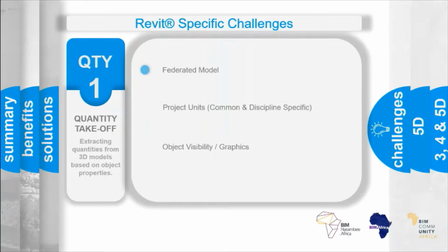It's also important that we manage the coordination of elemental ownership between the different design disciplines, and we'll need to address that in a BIM execution plan in order to prevent elements being duplicated or missed. Obviously, if an object isn't modeled, it can't be quantified, and likewise, a duplication in either discipline's drawings will result in an overcalculation.